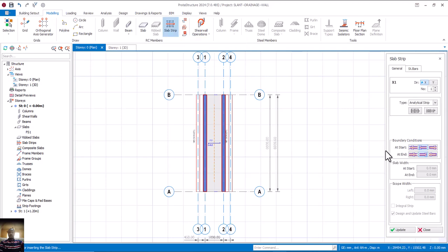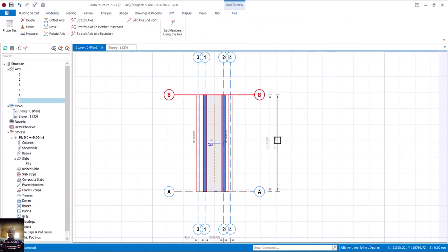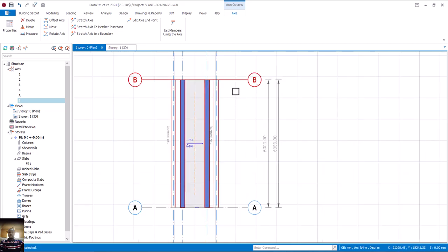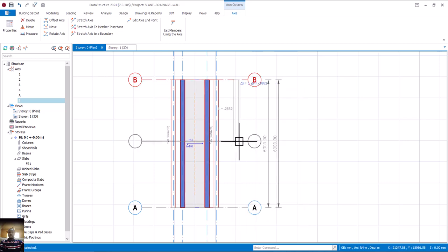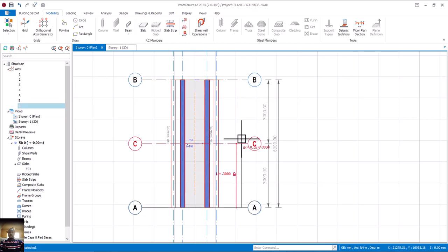Now at this point, don't forget, before I come to this place, I'll take this. The length is what? 3 meters. Sorry, 6,000 mm. That's millimeter. I'll offset it down with F2 by what? Minus 3,000 to give me the center. Enter. That's fine.